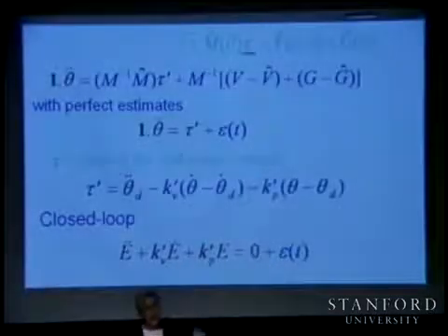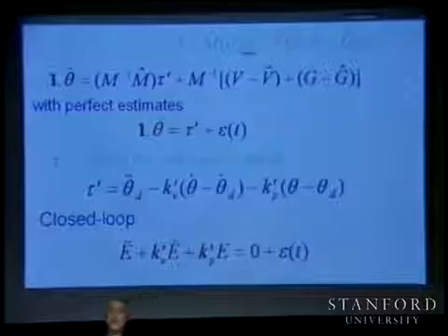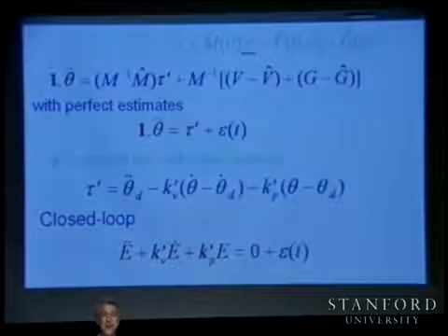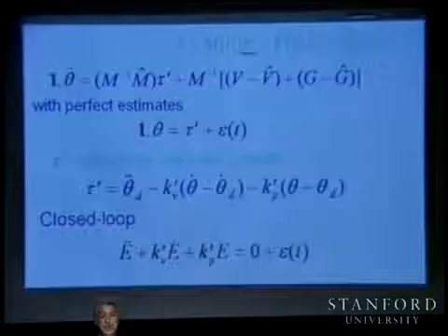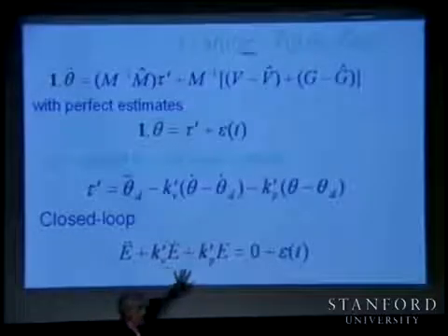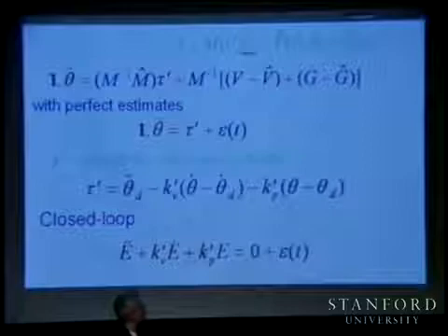Friction. There is actually nonlinear friction that is difficult to model, and there are a lot of other nonlinearities, and then you have the higher order dynamics that we are not modeling. We are modeling just second order dynamics. The flexibilities are not modeled. So you are going to find limitations here. You can try to compensate for part of the friction forces, but it's not going to be perfectly compensated for. So higher gains are very important here in practice.